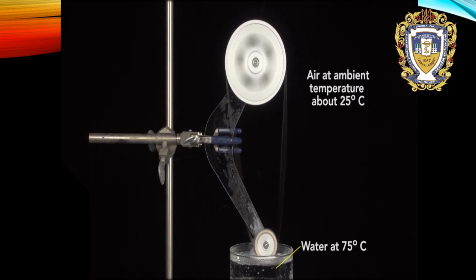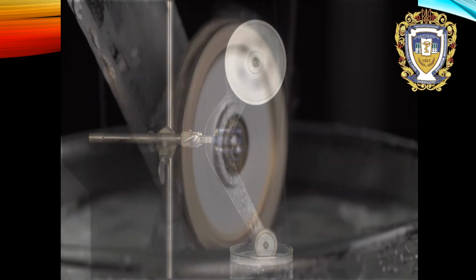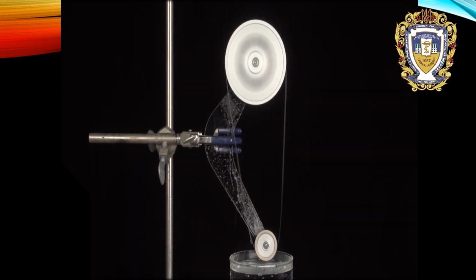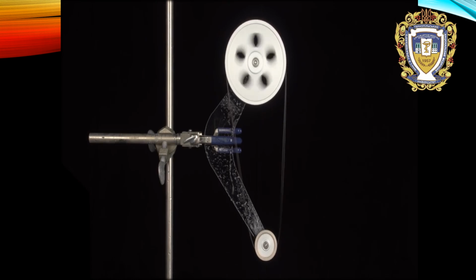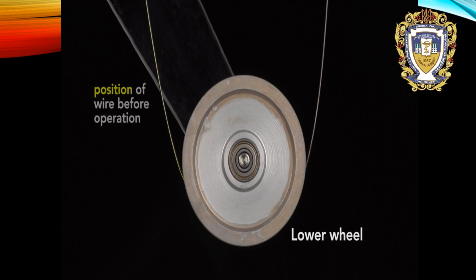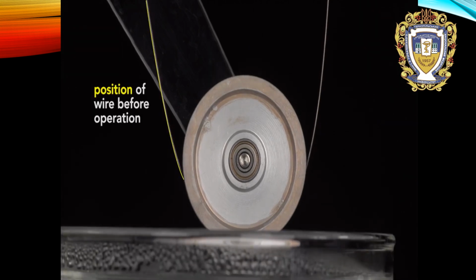It uses the temperature difference between the water and the air to power the engine. When I remove the water, the wheel stops spinning. This engine runs because this loop of nitinol wire was originally straight at a very high temperature, so as it's heated, it tries to straighten. To see how that causes the engine to operate, watch what happens as I contact the lower wheel with the heated water. I'll mark the position of the wire on the left with a yellow line.